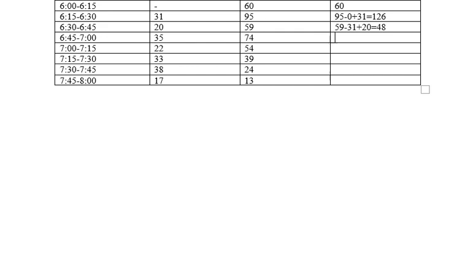Okay, so again for the next one it will be 74 the vehicles which left, minus 20 from the previous queue, because these vehicles were not new, they were already from the previous queue, plus 35 whoever is left in the queue from the present arrivals. So now the number is 89. Okay, so in this way we'll be calculating the rest of the numbers.